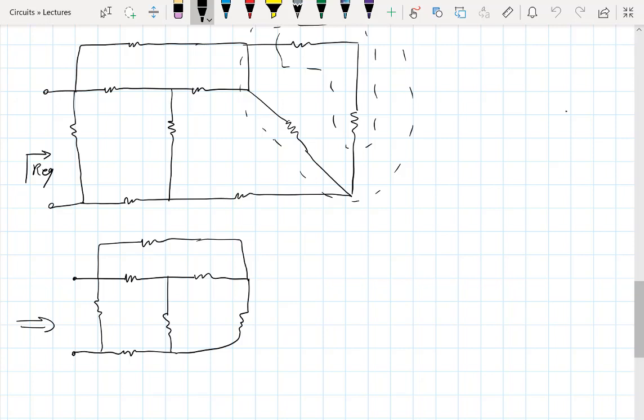So if I look at, let's start from the top. This top resistor here. Is it in series or in parallel with either one of these? No, it's not. It doesn't share the same current because there is another branch here. Remember, when I'm looking at an equivalent resistance here, it means implicitly that I'm connecting this somewhere else, right? For instance, to an ohm meter. Or I am applying a voltage, measuring the current, and the ratio of the two would be the resistance, right? In general, this is something I've put in a box, and I'm doing something else to it from here. So there is implicitly a current going into the circuit.